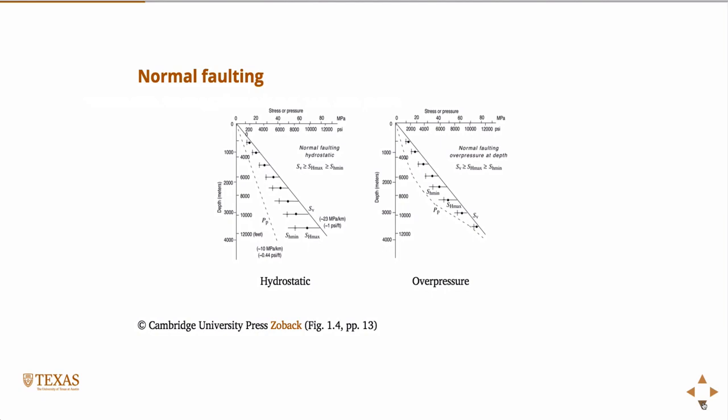So remember, in a normal faulting regime, what's the greatest principal stress? We learned it last time. No, vertical, right? Remember, I told you: normal, strike-slip, reverse. The vertical is on the diagonal of that table that I drew. So you can sort of draw the table in your head. So normal, the vertical. Also, if you just look at the plot, I had it written there. Okay. But anyway,